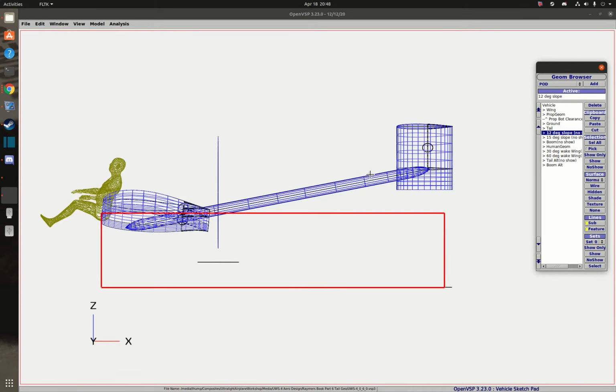Now, one of the reasons I don't like this angle is that this is going to be a little bit like a flying surface. And because of this angle, there's going to be a little bit of a down force. This is going to try to pitch it up a little bit. Now, that's not horrible. I could actually live with that, but that means my tail is going to have to be just a little bit bigger to counteract that pitching moment a little bit. So I'd rather not do that. I'd like to actually reduce this angle a little bit.